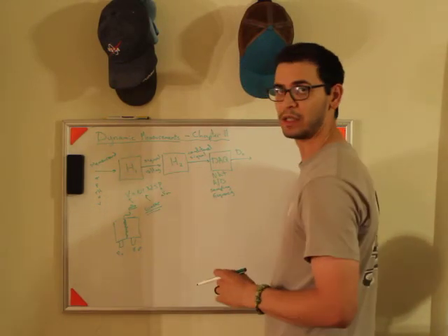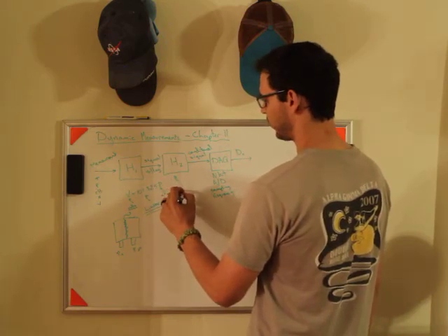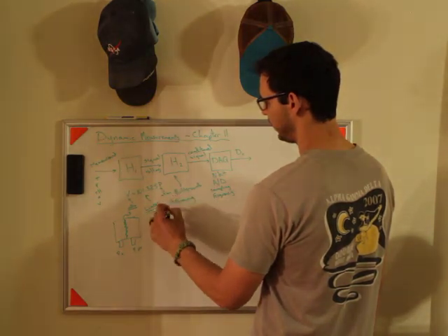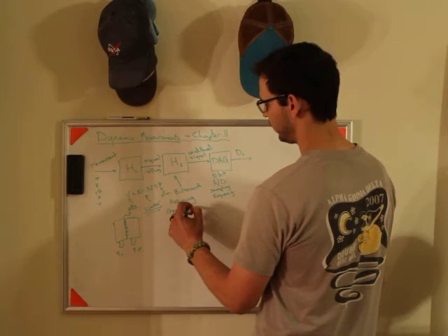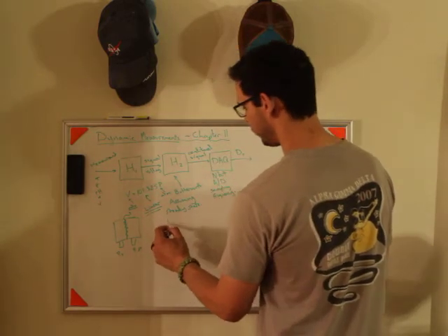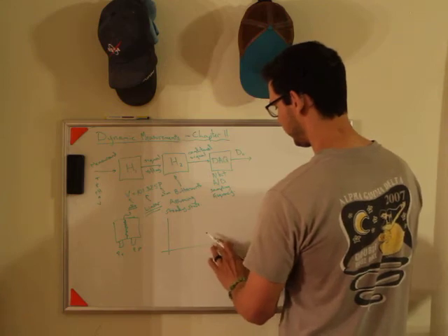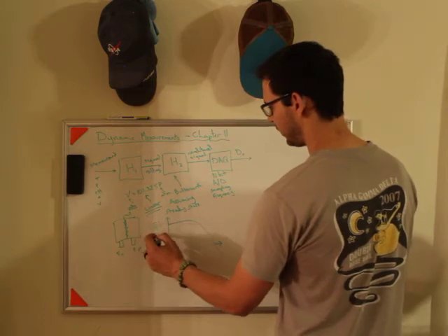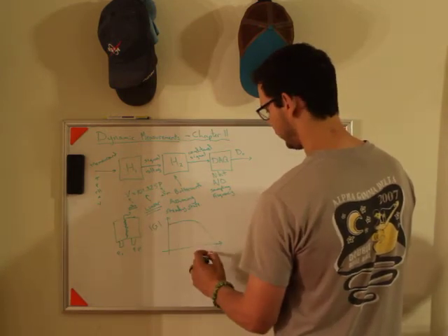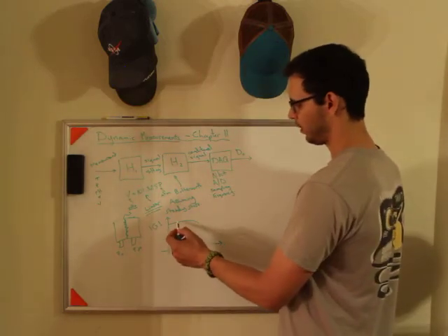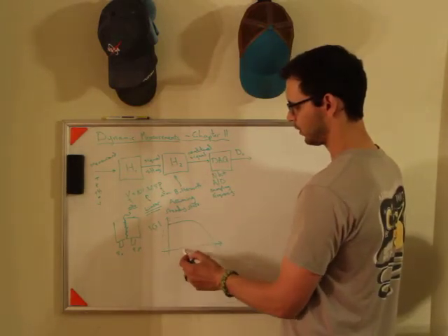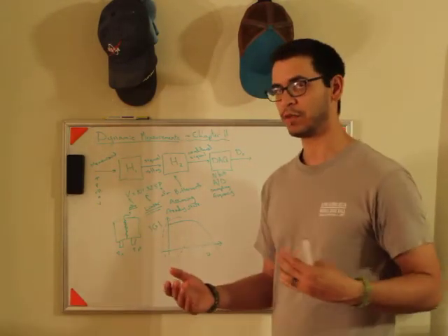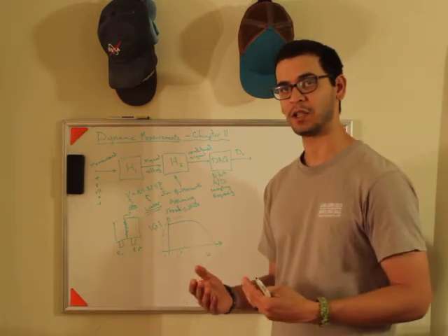When we do our signal conditioning here, when we did, like, say, the Butterworth filters, right? We were assuming steady state. And that is when we drew the Bode plot, right, and we drew gain and input frequency, we were assuming that most of the area of interest that we were looking at was over here, where the frequency was low. So this is like, you're flying in an airplane and the velocity is not changing that drastically.